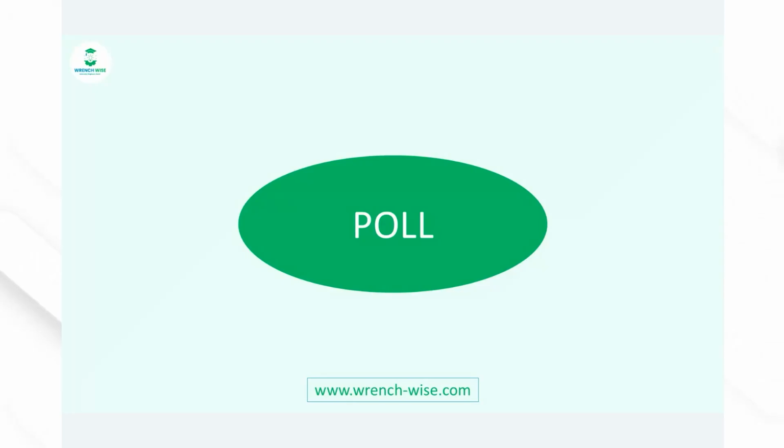Okay, one more poll we have. So for optically thin media, we choose the P1 model. What is the expected outcome? Optically thin media, this is tau closer to 0. What would happen if you use the P1 model there? Remember, P1 is much more diffusive, and in clear media, P1 might not do well. It's not that the simulation will fail to converge, but much more than that, the simulation will run, but your result will be bad. Because the P1 model cannot model directional beams, and in your clear or optically thin media, P1 essentially enforces diffusion, and that's where it will fail.